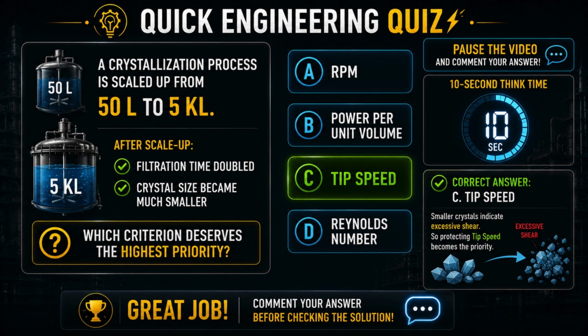Let's test your engineering thinking one last time. A crystallization process has been scaled up from 50 liters to 5 kiloliters. During production, filtration suddenly takes much longer, and quality control reports much smaller crystals. Which scale-up criterion deserves the highest priority? A. RPM. B. Power per unit volume. C. Tip speed. Or D. Reynolds number. Pause the video, think like a process engineer, and comment your answer below.